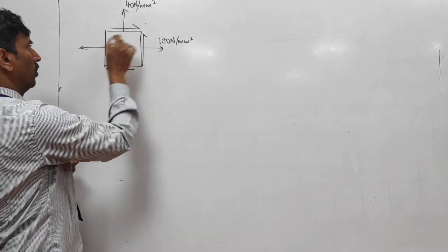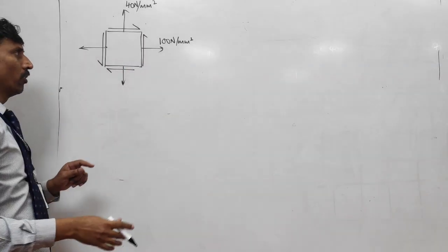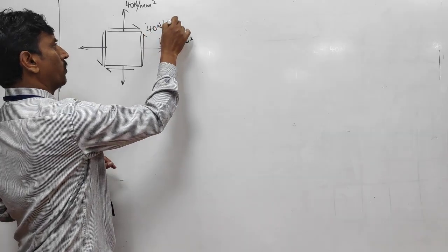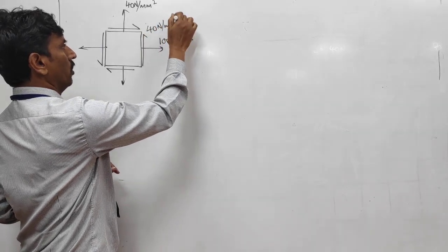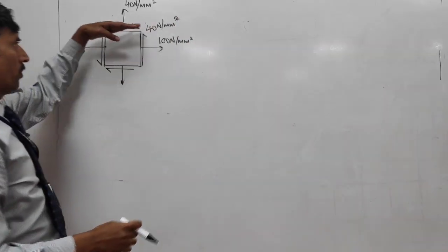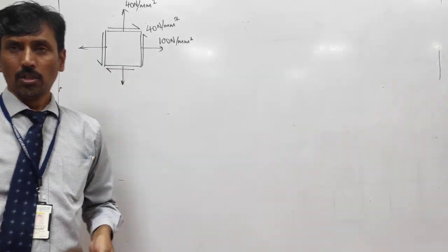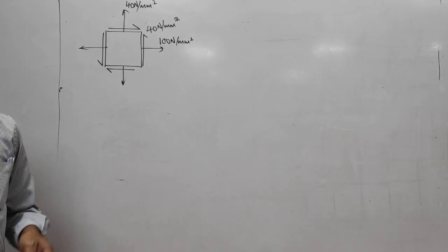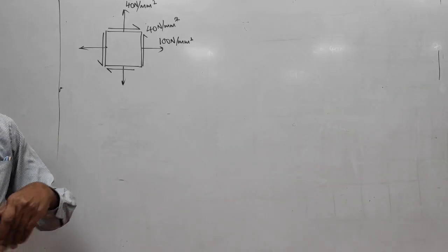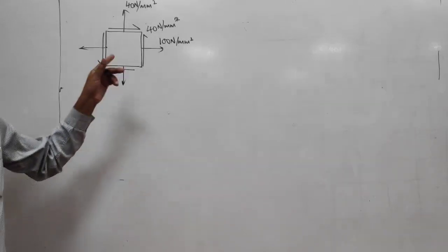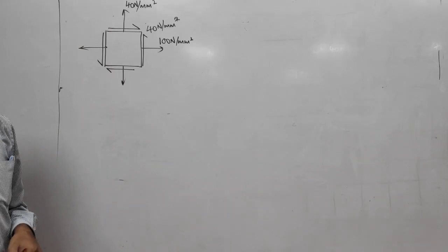And the shear stresses are only mentioned at one point. So the value of the shear stresses will not change on every surface. If one surface is applied with the shear stress, complementary shear stresses are automatically developed. So complementary, the word means it comes free. Okay. So that way it has the same value.